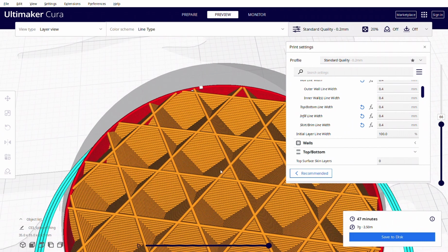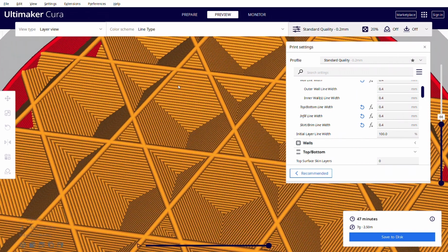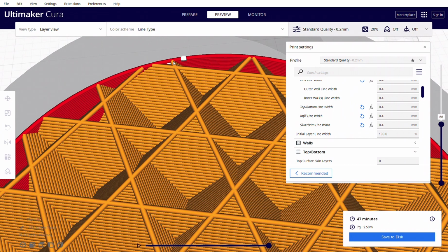Because this slicer is telling your printer to go here to form this wall, and if it thinks it's putting down a 0.4 wall, but really your nozzle is a 0.2, you're putting down a 0.2 wall. When it tries to connect things like these infill lines, this wall is going to be short in one direction or another. So this thickness isn't going to connect there. So that's why I'm saying it should always correspond to your nozzle width.